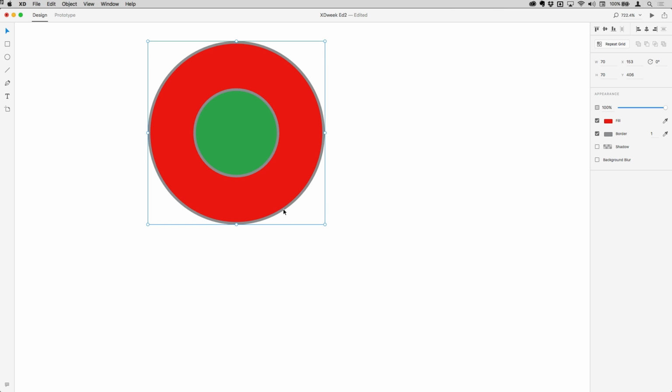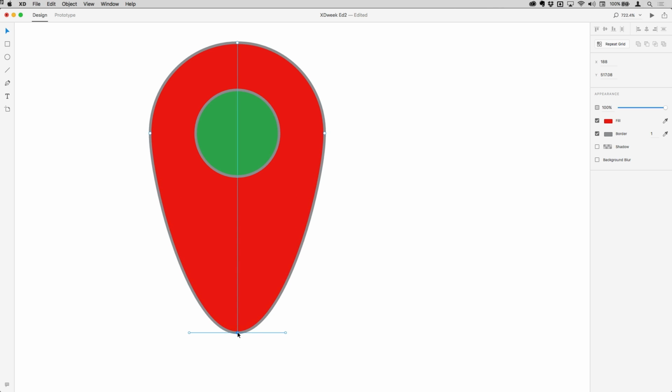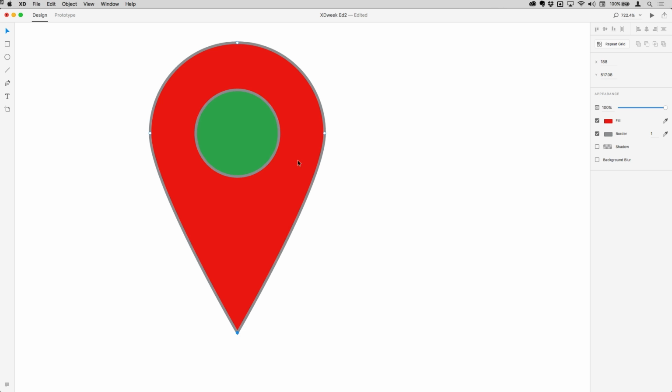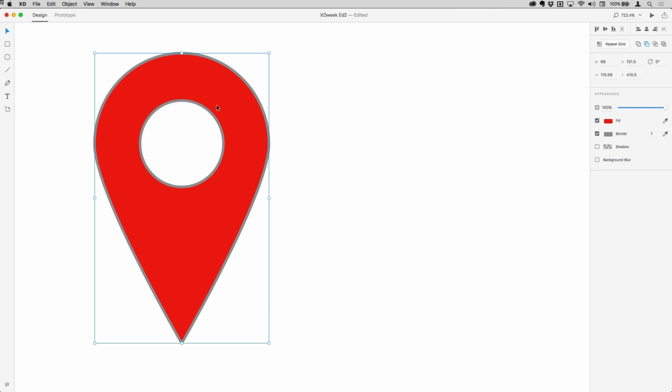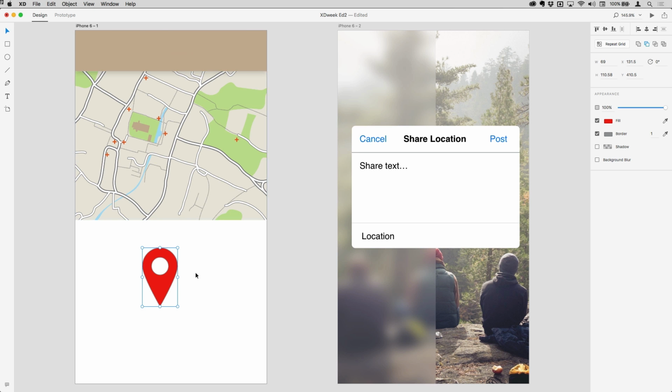First, however, I'm going to double click on the edge of this circle, which allows me to work with the individual points. So you'll see I can bring this one down using the Smart Guide to show me when it's in position. And if I double click on the point, that changes it to a corner. If I now select both of these things and select the Boolean subtract, then that will drop that out, and I've got one single shape that moves around. Let's go for the whole artboard so you can see things through it.